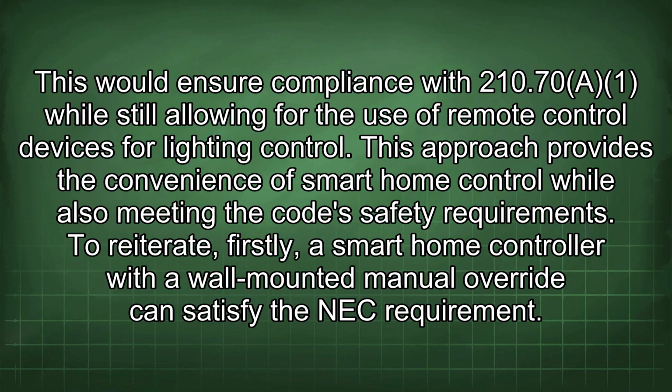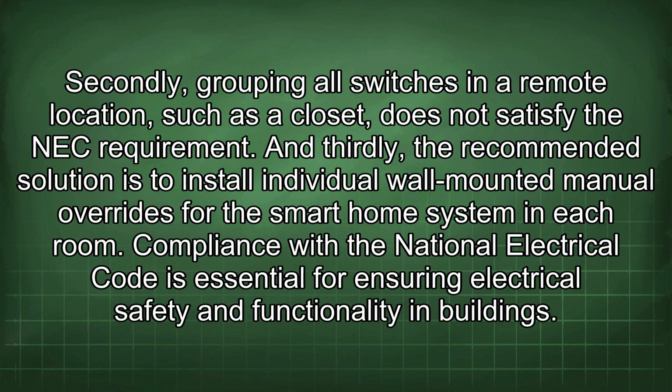To reiterate, firstly, a smart home controller with a wall-mounted manual override can satisfy the NEC requirement. Secondly, grouping all switches in a remote location, such as a closet, does not satisfy the NEC requirement. And thirdly, the recommended solution is to install individual wall-mounted manual overrides for the smart home system in each room.